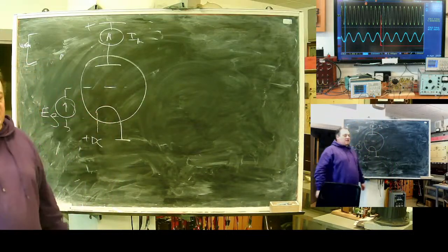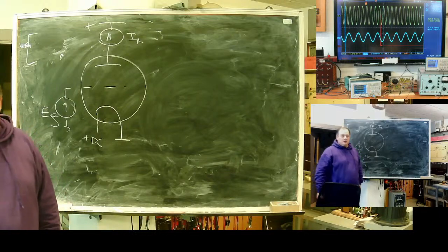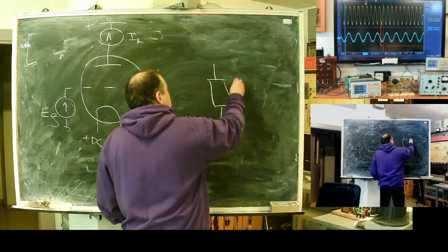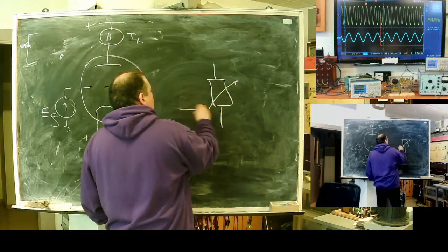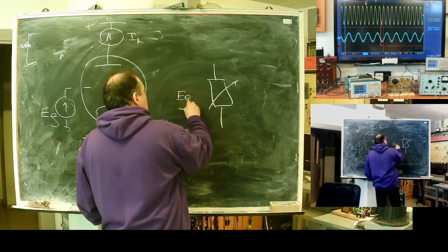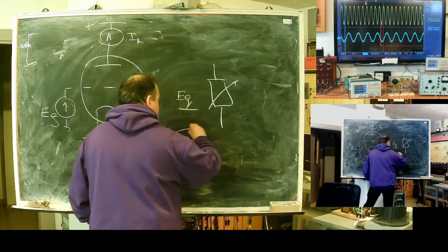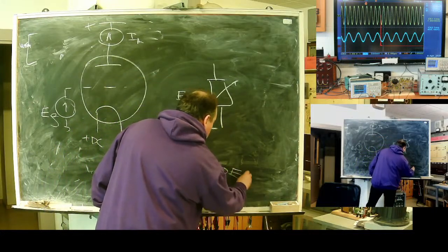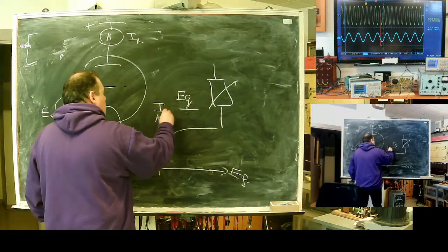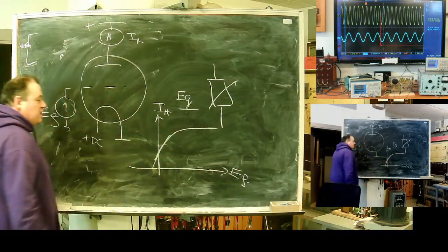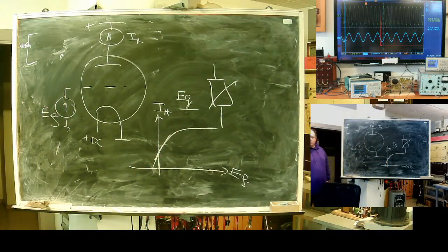How can I represent my triode? As a resistance controlled by a grid. The grid voltage is unknown. And I use this linear part of characteristic to perform a voltage amplification, to act as a linear amplifier. Yeah?